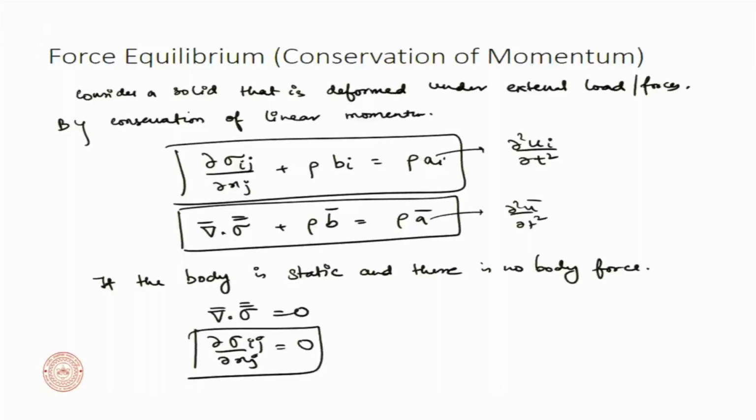So if we had the final force, or the force applied, divided by the deformed area, then it was the Cauchy stress tensor. If we had the final force, or the applied force at that time, divided by the undeformed area, then it was called the nominal stress. And if you had a projection of the final force onto the initial frame of reference and applied on the undeformed area, then it was called the material stress. So PK1, PK2. All right.